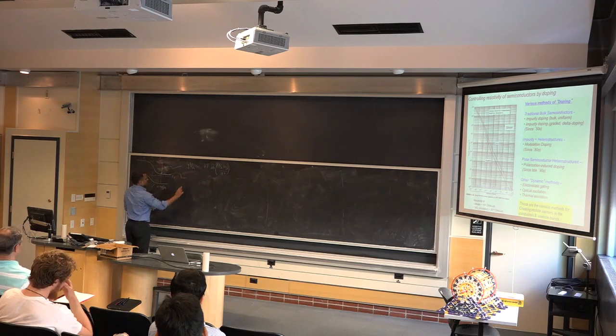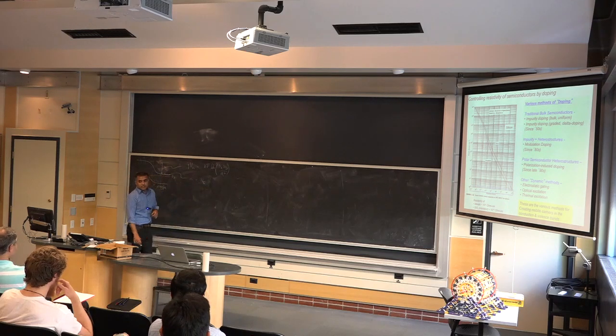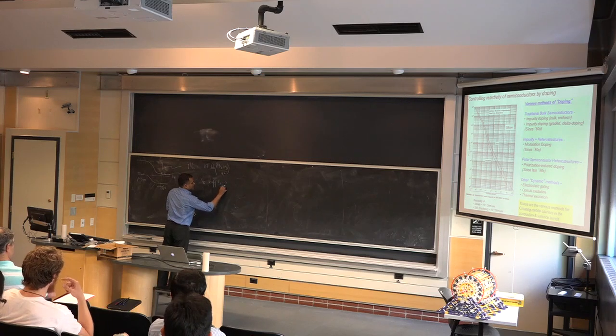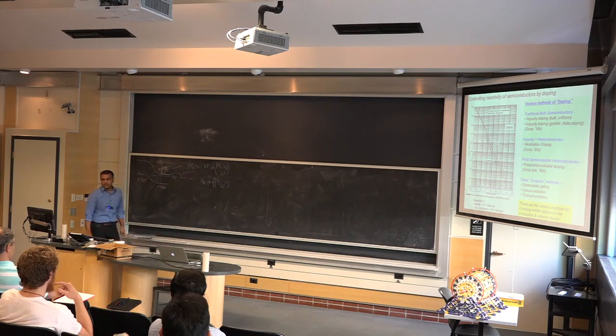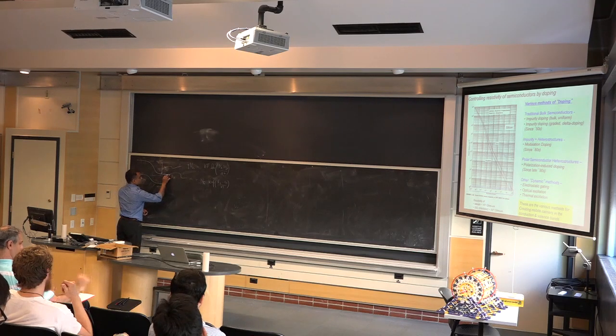And how many electrons I have far away from this junction, we saw that in general, I can always write n equals N_C, the conduction band density of states, which we did in the last class, times an exponential of (E_Fermi minus E_C) over kT. We wrote that in the last class. How far is the Fermi level from the band edge? This is the band edge.